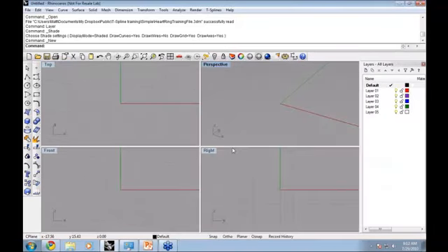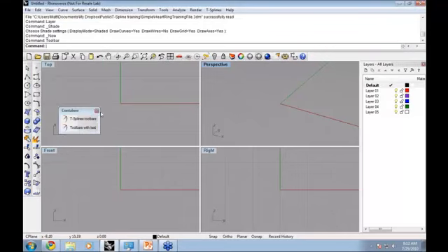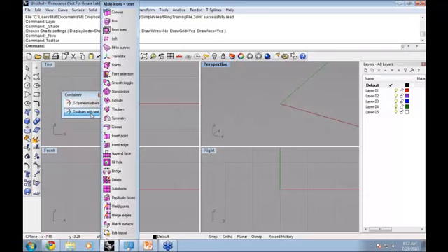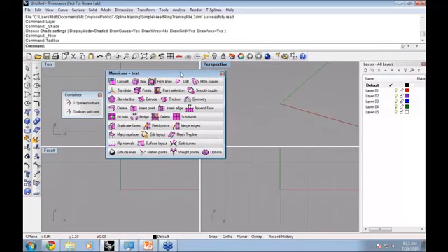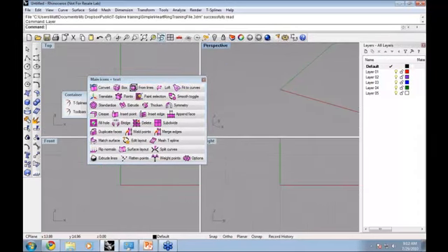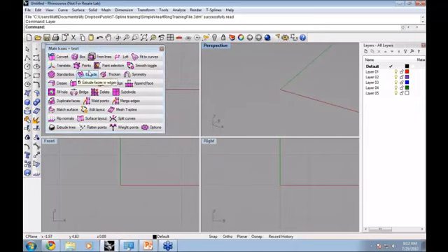The extrude command is something that can be used. Let's pull up my T-Splines toolbar. Let's type toolbar and pull up T-Splines, and I'll use my toolbars with text for the webinar so that you can see what I'm using. Let's close this out. So here's our extrude command, and it can be used on edges, faces, and also on lines or curves.